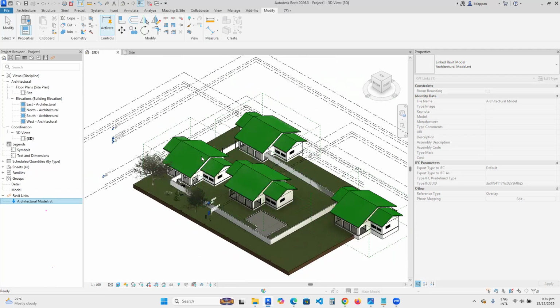or it can be made up of 5 types of buildings or 10 types of buildings, which means that you are going to model each of the buildings separately. So building 1 is a different file. Building 2 is a different file. Building 3 is a different file. Building 4 is also a different file. Good. Then you model only one site file. Then when you model the site file, you know where you are going to place building 1, building 2, building 3, and so on.